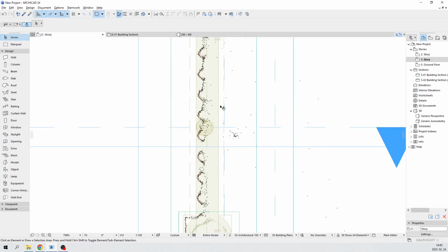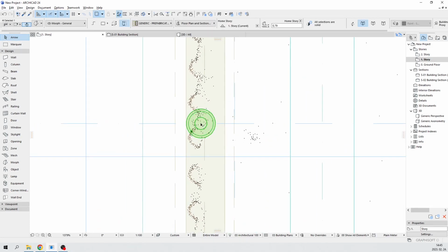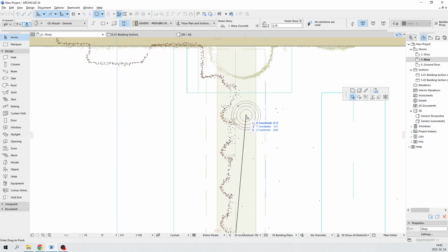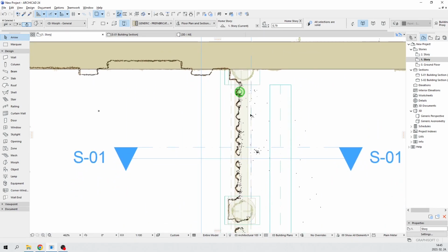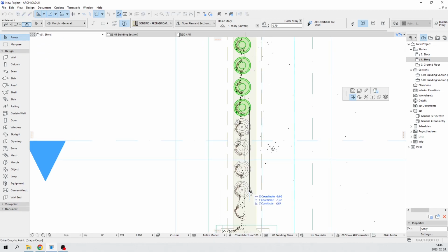So we have this small balustrade. We are using the same method. I'm not gonna copy 100 times basically, so we are using the multiply option in order to create the right amount of balustrades.